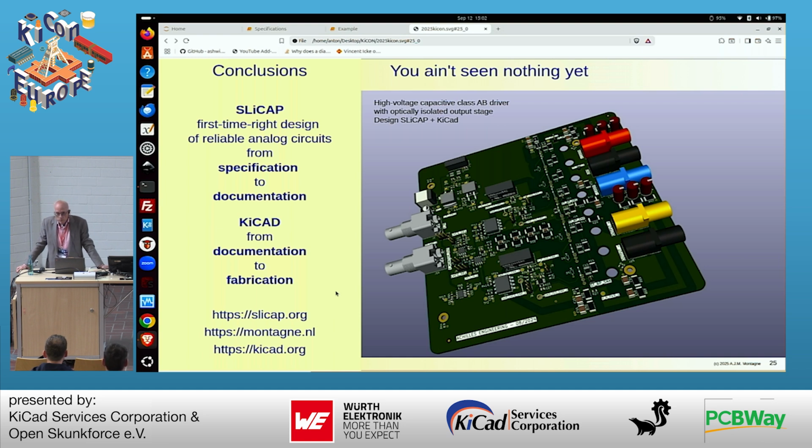But usually what you do is you make a small signal equivalent circuit of your power supply, and there's also root locus techniques included. One of the strong points of SLiCAP is it doesn't give you any false poles and zeros. It calculates with integers, and it uses the most horrible method, which is very good for symbolic calculation of the determinant of matrices, which is just Laplace expansion, but it's still fast. But yes, you can do this for this as well.